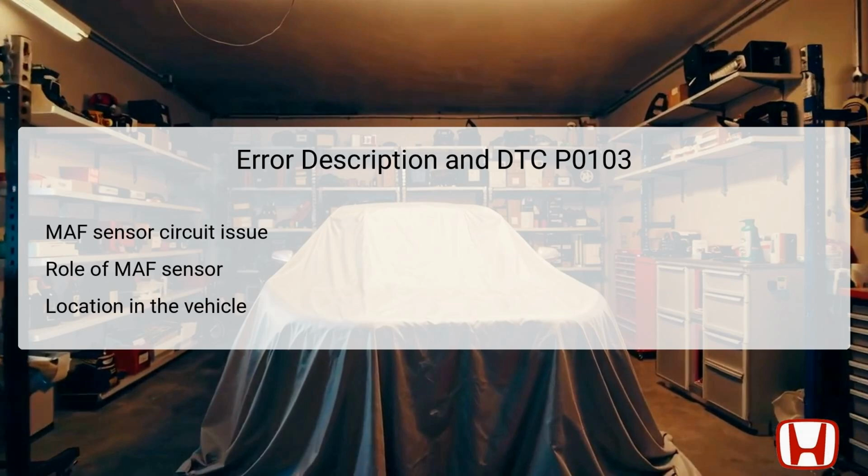If the circuit experiences high voltage, it often indicates a malfunction, whether due to faulty component performance or electrical issues such as short circuits or poor wiring. Identifying whether the DTC is confirmed or pending is crucial, as it informs the next steps in the troubleshooting process.